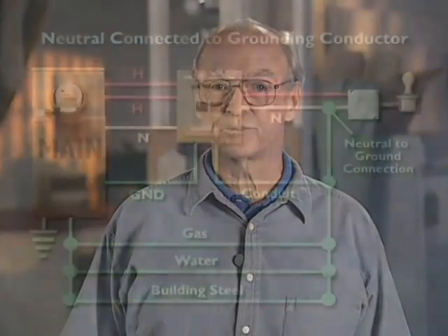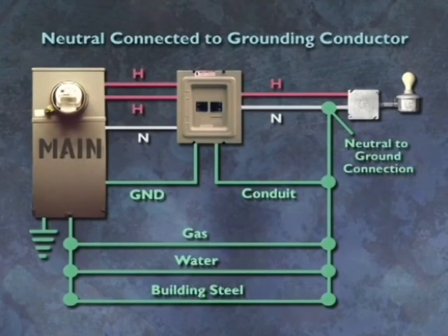The 1993 NEC Handbook points out the possibility of arcing in concealed spaces leading to fire, and the shock potential to workers. When a neutral is connected to the grounding conductors, it will travel in all available metallic pathways which lead back towards the service entrance point.